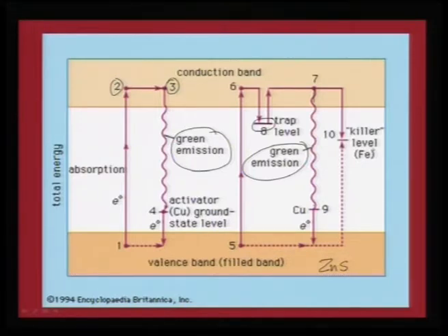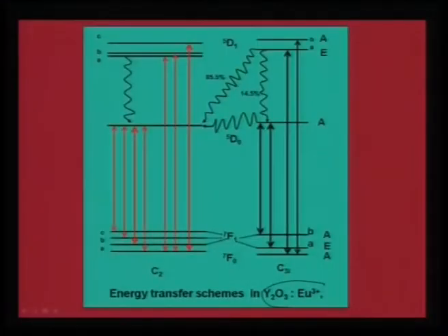If we have very little amount of iron that is coming out as an impurity, then this can actually act like a killer. So, this is called a killer level, because any other impurities which are in same comparable atomic level can actually bring about quenching of this light. In the case of emission that is happening in the red light based on europium oxide based phosphors, there is a unique issue that is involved.